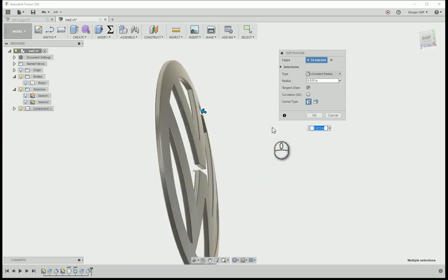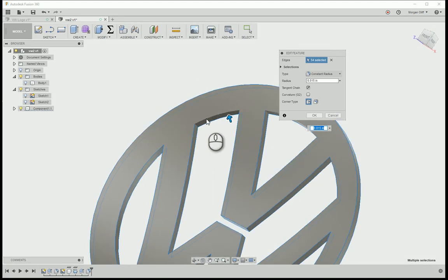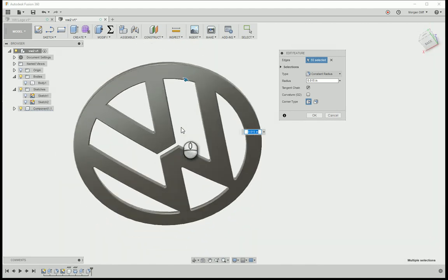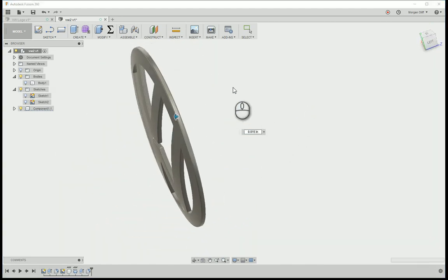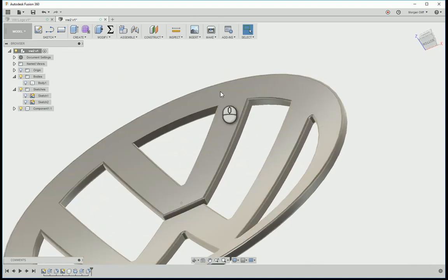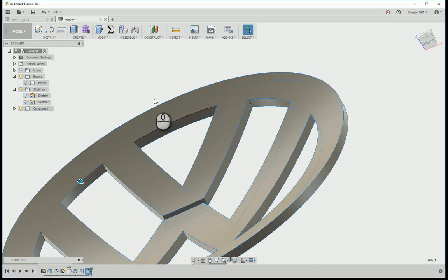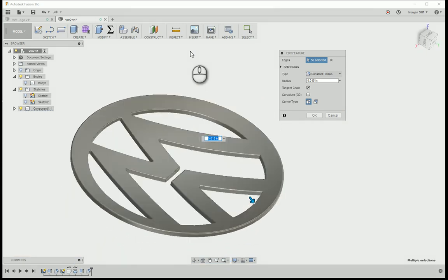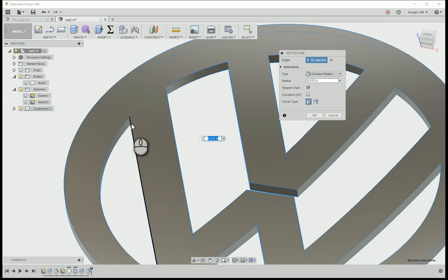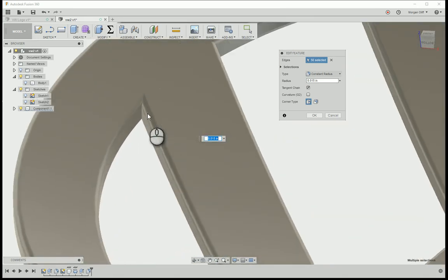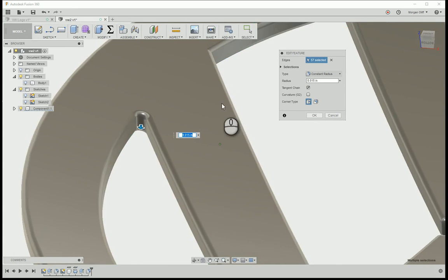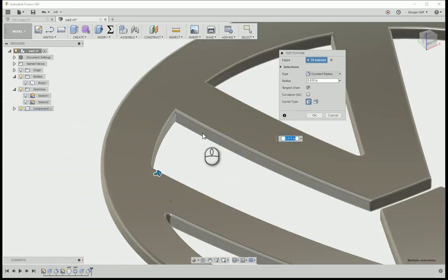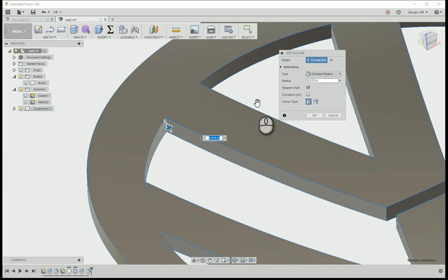That's not as reliable of a tool as I experienced earlier. It's a little bit frustrating. In the model before, literally, I just did a window select, and it had no trouble at all grabbing every single edge, which is what I want. Good enough. The main thing, the reason I'm actually putting these fillets on is because I want to catch these inside corners where I would have to reach with a small cutter. And with the corner radius, of course, you can just program it, and it'll leave whatever radius the cutter leaves.